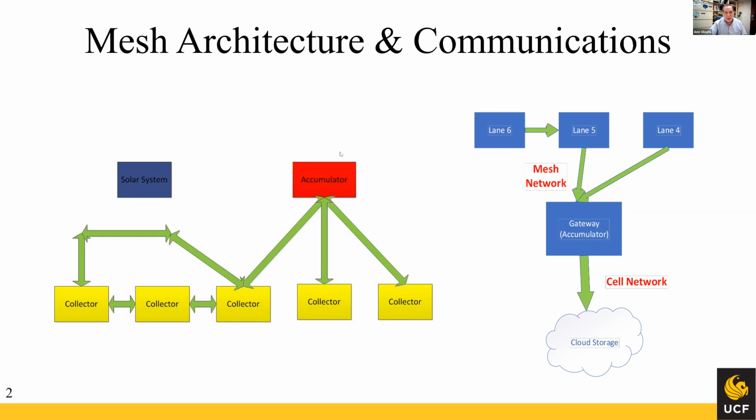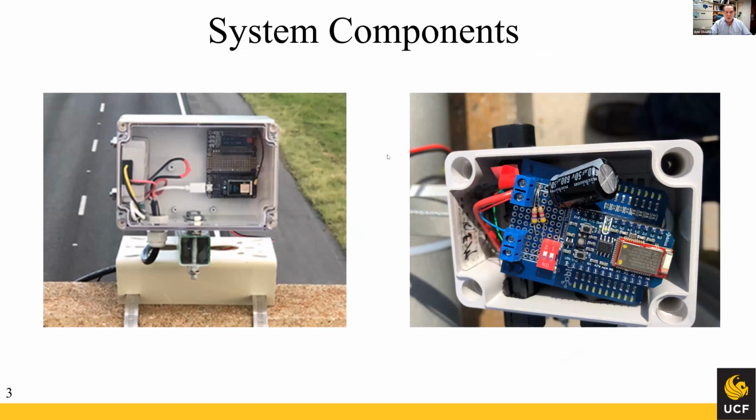Now, we can, of course, collect this type of data, which is primarily the type of vehicle, whether it's a car or a truck, and potentially the speed of the vehicle, to detect congestion. We easily could have done that through Doppler radar. Doppler radars tend to be very expensive, and the infrastructure to install them is rather expensive. So instead of using that, we settled on using individual lidars, just single-ray lidars, each connected to a small microcontroller running a mesh network. The data is collected through the mesh network, primarily through these collectors that you can see on your right-hand side.